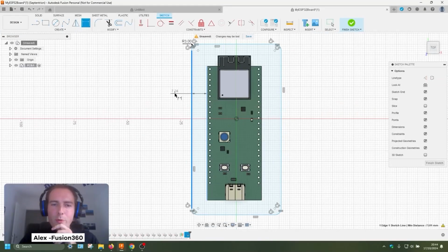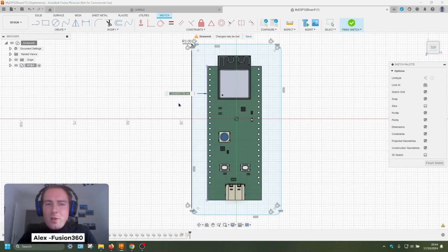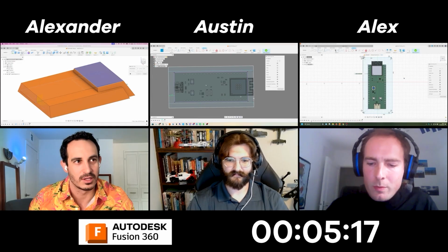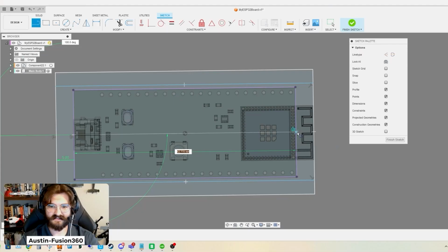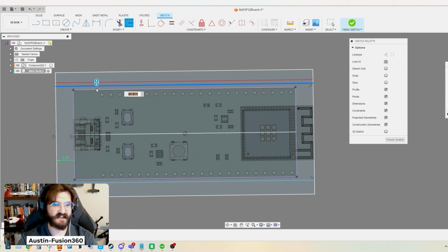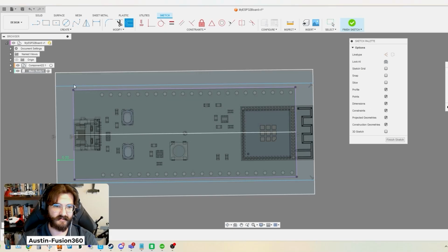I don't know, but you guys always have the habit of first drawing the enclosure as a big solid to get the final external shape that I want, and then hollowing it out and doing everything else. Is that what you also do? That's what I'm doing. Pretty standard, I think. Set up the outside perimeter and then just shell it, and yeah, exactly. It'll copy the drafts and whatnot.